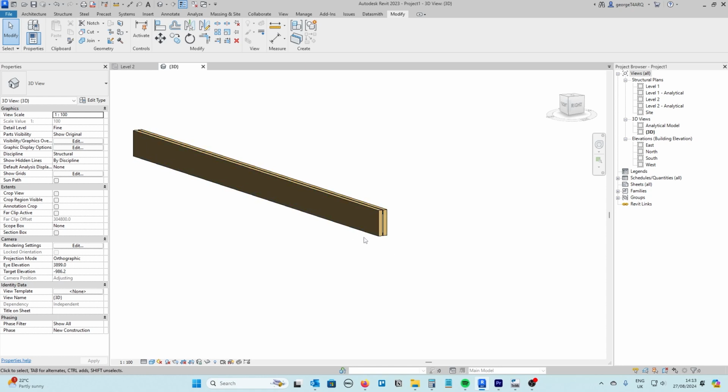Another advantage is with the timbers being either side, it makes it a lot easier for the builder to fix new joists or rafters, whatever it is, which in this kind of construction are likely to be more timber elements or framing elements to be fixed into the side of the timbers.